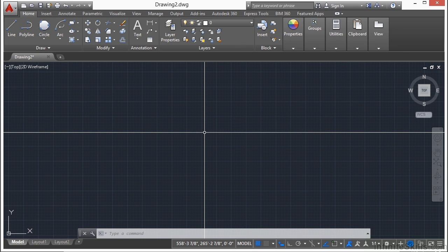There will be times when you need to create what's called a polygon. A polygon is a multi-sided closed shape. In AutoCAD, it's also a closed polyline. Now, there is a command called polygon. With this command, you can draw shapes from 3 sides all the way up to 1024 sides. Typically, you would probably only draw from about 3 to 10 sides, but it's good to know that you have options. So you can type on your command line the word polygon to get to the command.